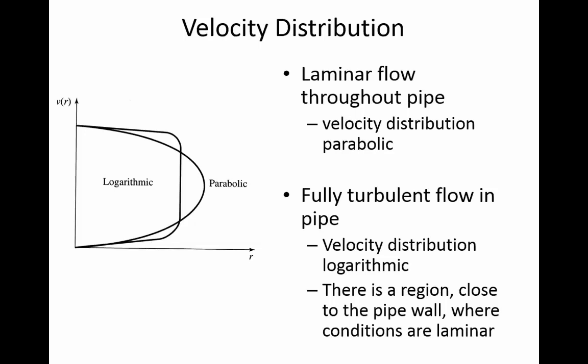But on average, it's going to have the shape that is depicted on the screen there. The faster the water is going, if you have a really high velocity, then this linear front will go further and further towards the edge of the pipe. So even this logarithmic shape is subject to change based on the flow velocities in question.